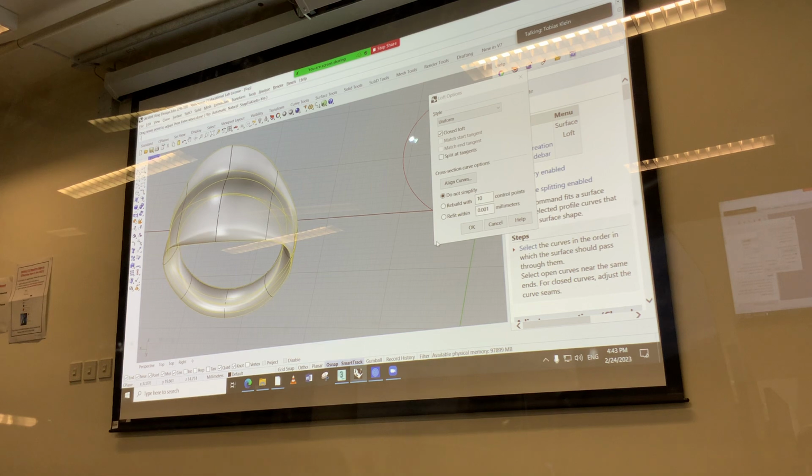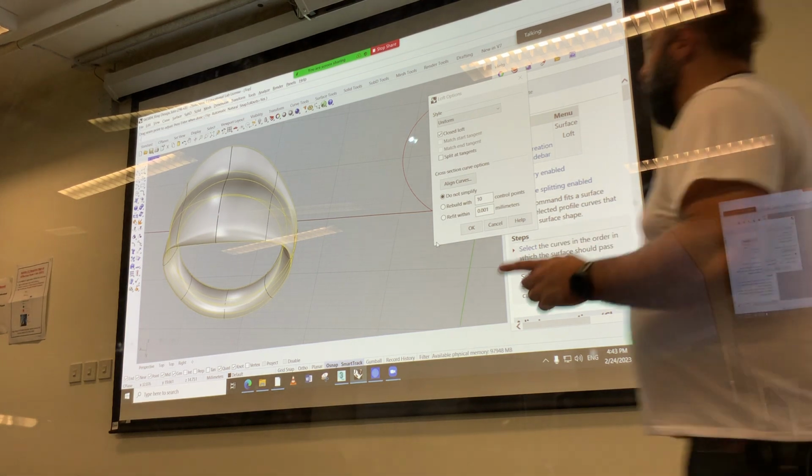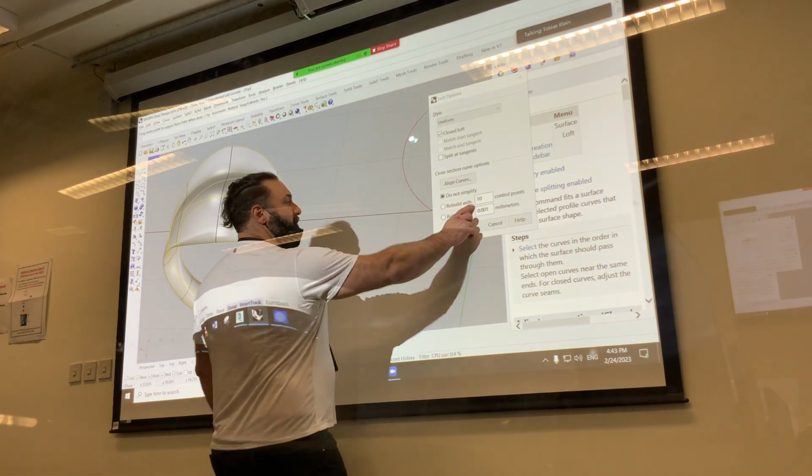Because this has all to do with either precision or the purpose of what you're using it for. And our purpose is to make something in Rhino that is really specific to Rhino and then push it into another software to do something with it that's really specific to another software. So we want a perfect one surface, not 4 surfaces, that is very elegantly symmetrical and that we can very elegantly mesh into something where we get only quads out. So what we need to do is rebuild this here.